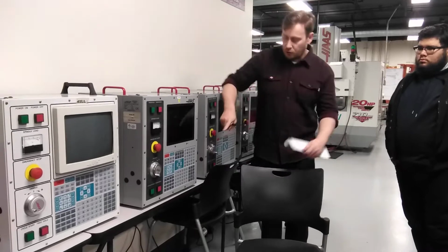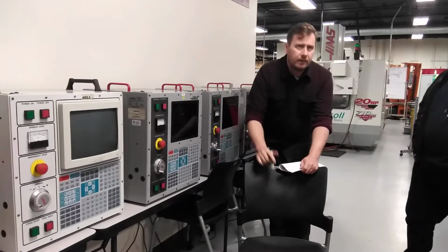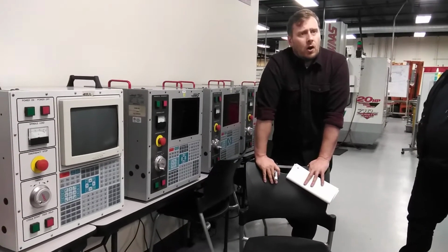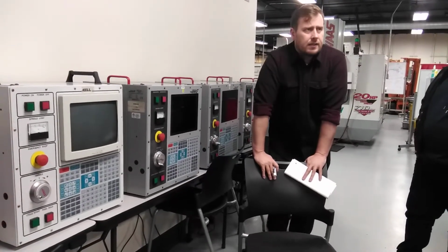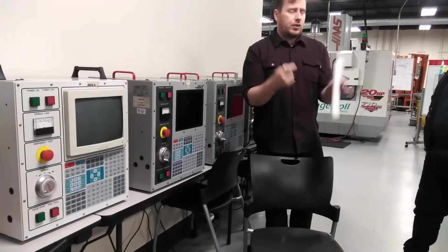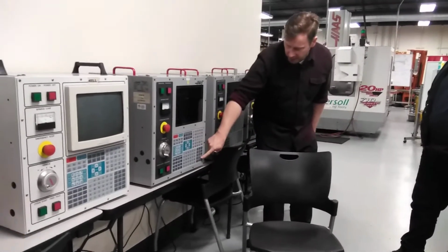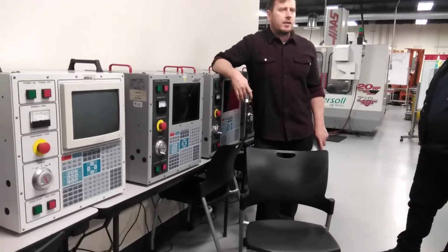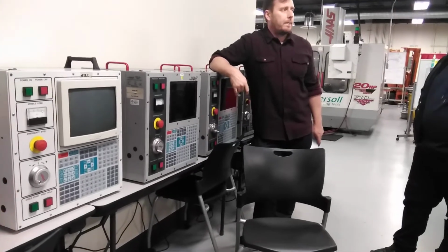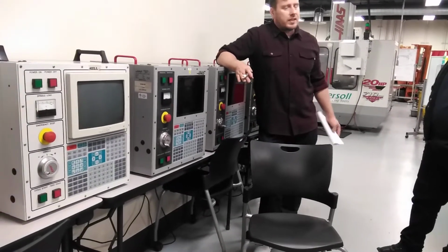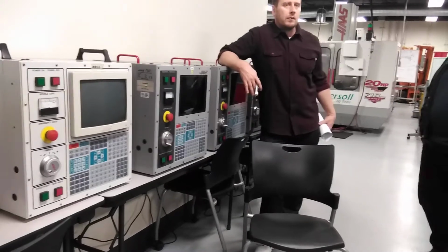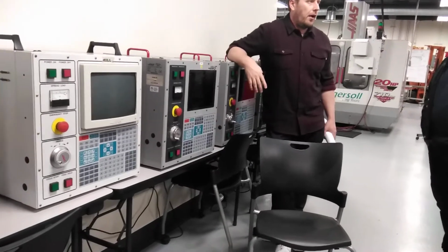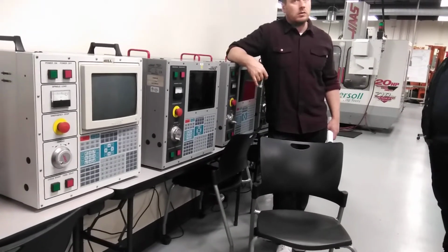Right? The wear column to the right is where you make any adjustments. So if your part comes out oversized, you measure that 4-inch dimension and it's oversized, you just put in a minus number. And the machine will take off another 5 thousandths if you run the tool again. So you don't have to adjust anything in your program. You just adjust the wear, and the machine takes control. Right? It's a very powerful tool.